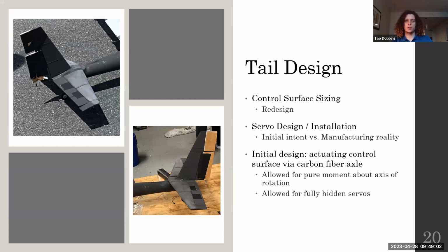So this is our maiden test flight design. One thing that we ended up doing is we had a feeling that we were going to be a little tail heavy when manufacturing, so we experimented with a smaller vertical stabilizer, but ended up being uncomfortable with the scale of it, so we decided to extend it back to the original design using foam board.